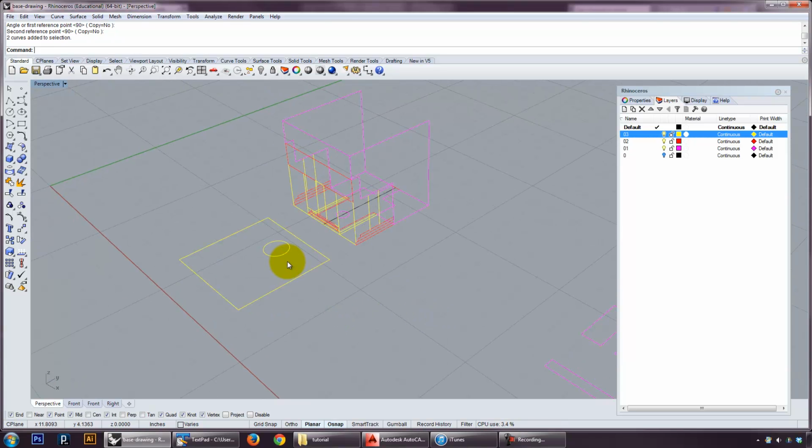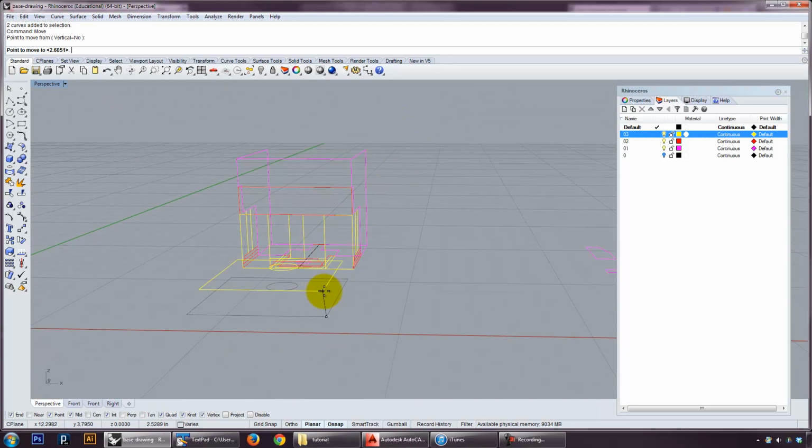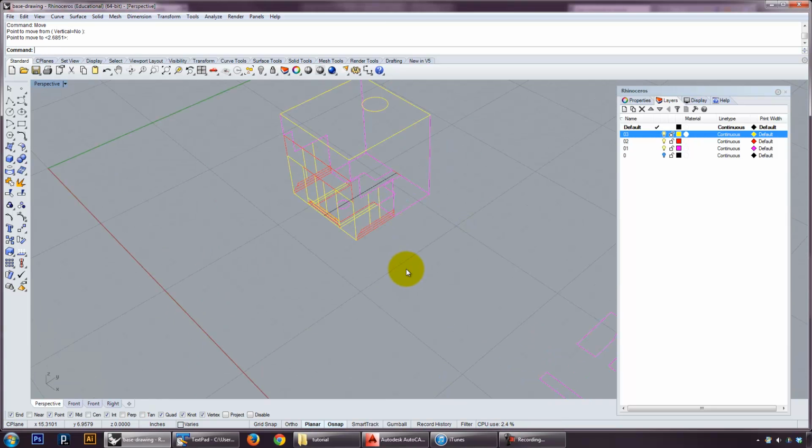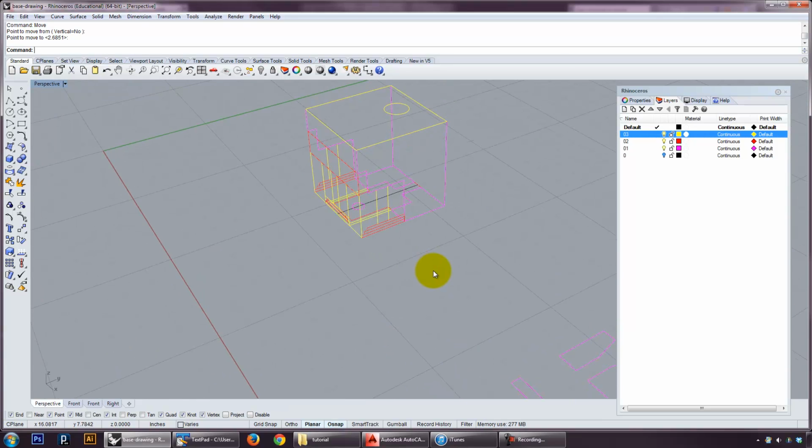The last piece of this puzzle without the section is going to be this roof plan. Now here I'm actually going to snap in 3D because I'm going to pick this corner. If I choose this corner here that's in 3D, you notice that it moves up and it moves in the X and the Y. That's one of the nice things about 3D, that you can get snaps in 3 dimensions, but it can be bad because it can cause you to snap to things you don't want to, so you have to be really careful about how you do that.